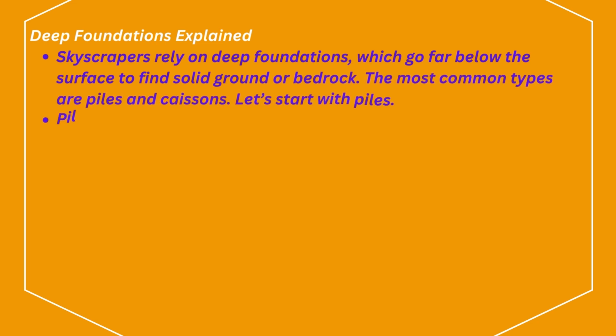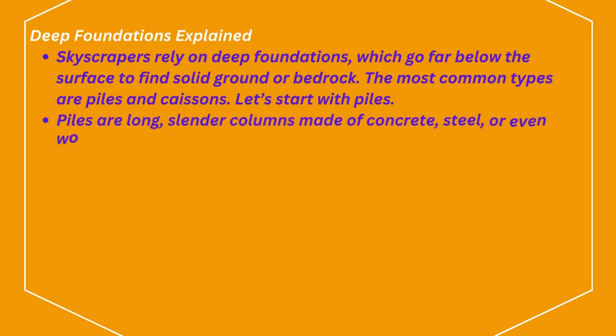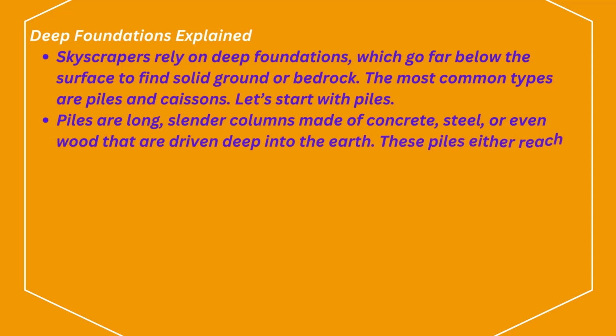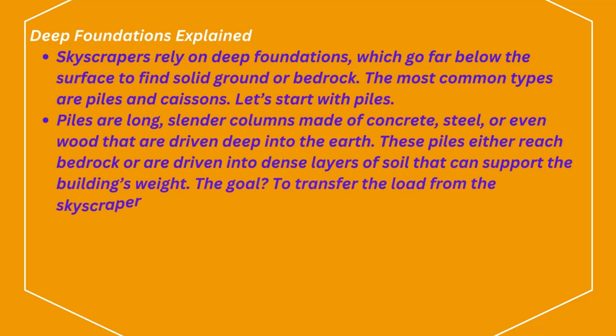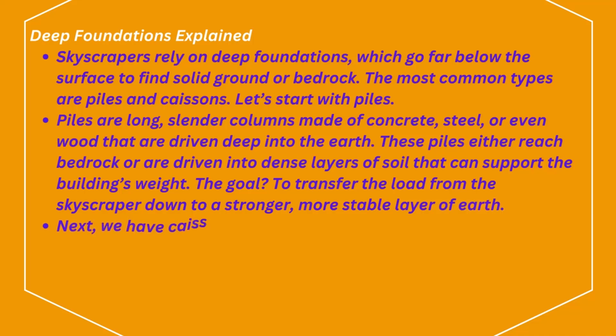Let's start with piles. Piles are long, slender columns made of concrete, steel, or even wood that are driven deep into the earth. These piles either reach bedrock or are driven into dense layers of soil that can support the building's weight. The goal? To transfer the load from the skyscraper down to a stronger, more stable layer of earth.